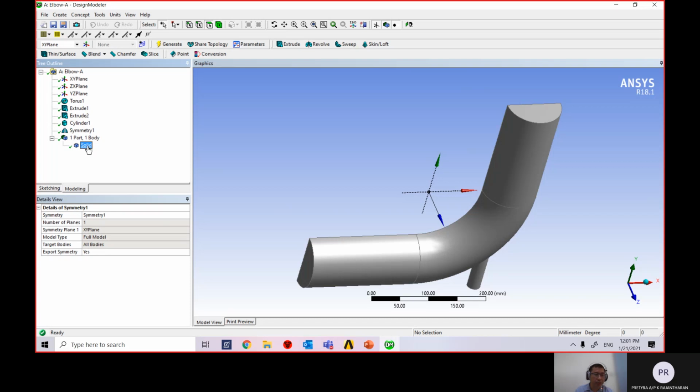So what we do is I click the solid here. Left click, the body will become yellow color or light green color. We want to change, because we're going to simulate flow, and all the flow will go through all this body. So not to confuse us that we are simulating solid, we're going to change this name to fluid.